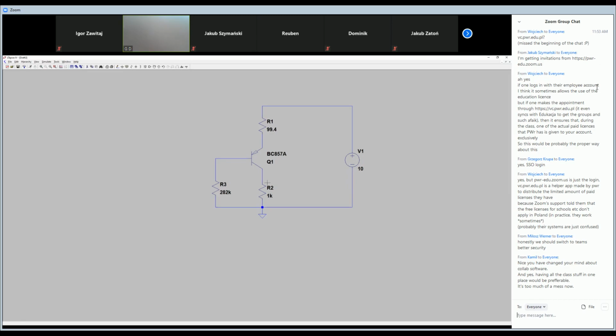And let's check the voltage drops and the currents. First of all, we have to run the transient simulation, of course. Stop time, let's put here 100 milliseconds. Start saving data at 50 milliseconds because we want to observe the steady state, and the maximum step time is 1 milli.